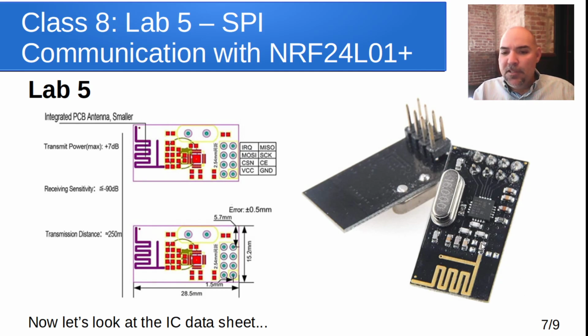But again, here's what those look like. You can see that PCB trace antenna that's on there. It squiggles back and forth to get it to be exactly the right length needed for the 2.4 gigahertz spectrum. It also has what they call an inverted F design, which really just looks like an F. But you'll notice that this part here adds what's called counterpoise for this part over here. There's a certain geometry for designing these PCB trace antennas that is based on the frequency, the length of the antenna and the surface area. And that's getting into something more complicated than what we want to do in this class.